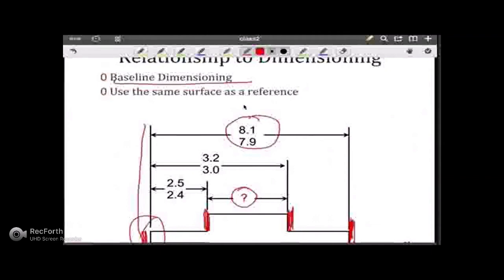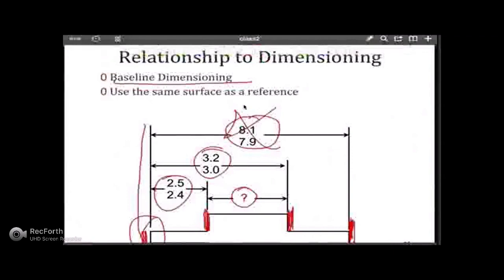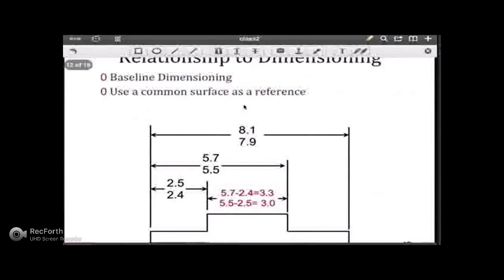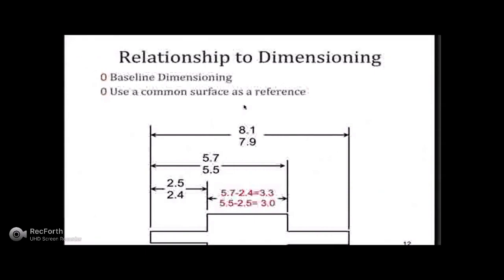And here we note that, first of all, this has no effect on the tolerance stack-up. So that's one of the first things that you really have to determine when you do a tolerance stack-up. That is, what are the features that are involved in this condition and how do they ultimately affect that part feature that I'm looking at. So really all we have to do is concern ourselves with these two features, and in this case we can see we're subtracting to get the difference, and if that's true then it's going to be slightly different when we go to our worst case scenario. So let's take a look at that.